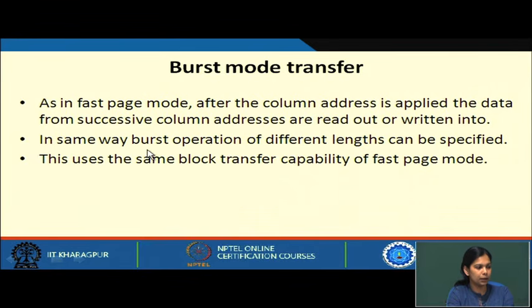In the same way, burst operations of different lengths can be specified. Burst operation means a burst of data, a set of words being transferred. So, here we can specify how many words we want to transfer. For the burst mode transfer, different lengths can be specified. This uses the same block transfer capability of the fast page mode. Whatever we discussed in the fast page mode, this block transfer mode also uses the same feature.